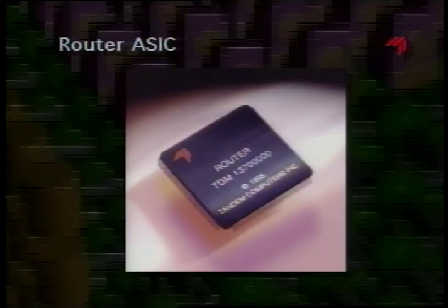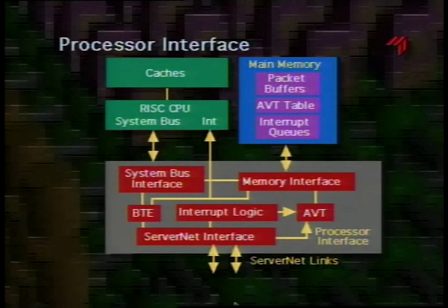The router is physically implemented in a 240-pin quad flat pack, and it includes just over 100,000 gates plus the random access memory used to store the routing table. The routing tables themselves are initialized through the maintenance system through a scan path used to configure the network. The X and Y paths through the network are configured at power on or when a node is added or deleted from the network.